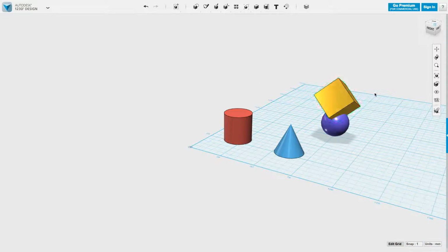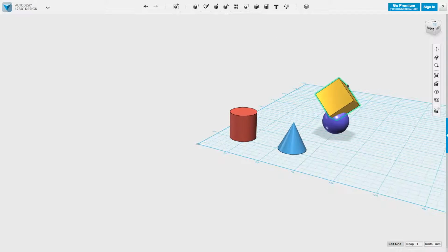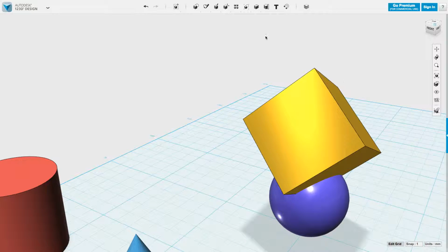To combine or to subtract, this is the same tool. We go into the combine menu. Oh, I'll just scroll in a little bit more. Okay, and with the combine tool, we have merge as an option, subtract, or intersect. Now I'll show you what each one of them does. So the merge will make both of the objects appear as one, and then when I highlight an object, both of them will be together. Subtract will essentially leave whatever I choose to leave as what's remaining, like the difference. And the intersect only keeps the overlapping parts, much like its description.